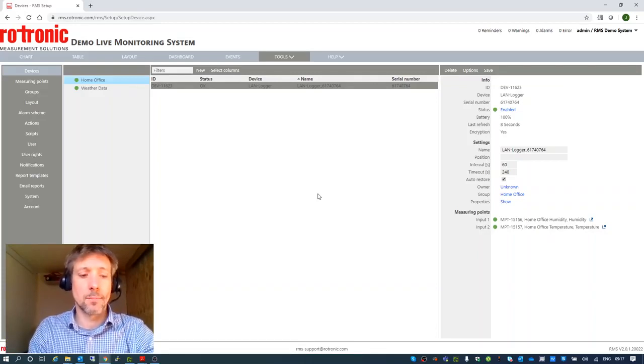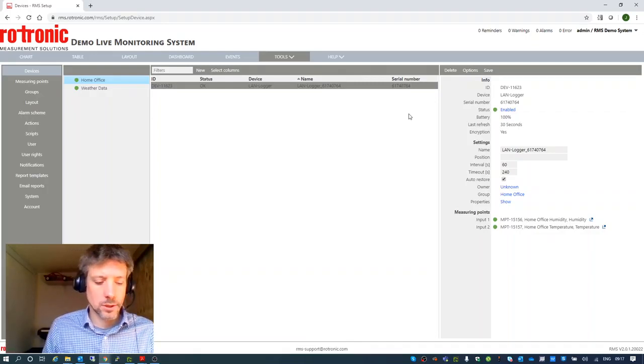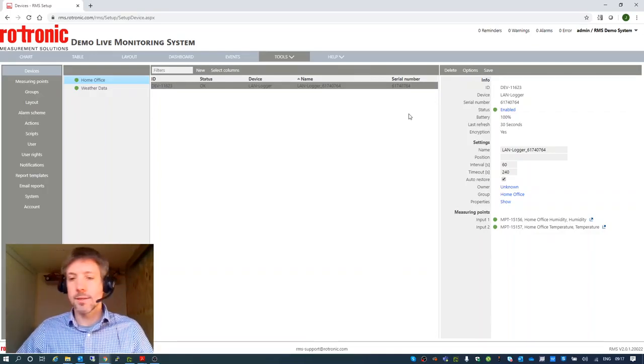Part of the design, well, the main design principle of the RMS system is built around the GAMP5 guidelines, and it's a risk-based approach. So we made a decision early on in the development of the system to use a dedicated wireless network. So we use an 868 megahertz frequency in Europe, 915 in America and other parts of the world. So that means you've got dedicated gateways for your wireless devices. So this is what we have here. So if your Wi-Fi password changes or if your Wi-Fi is overloaded, it doesn't impact your monitoring system.